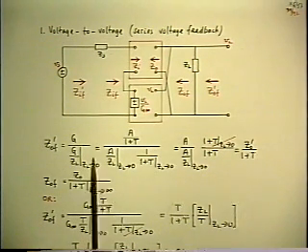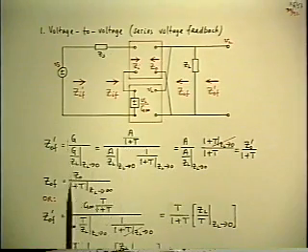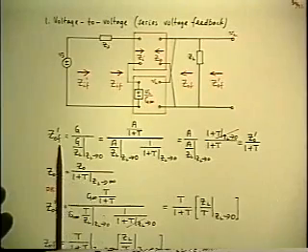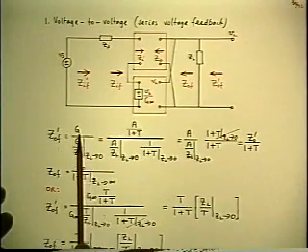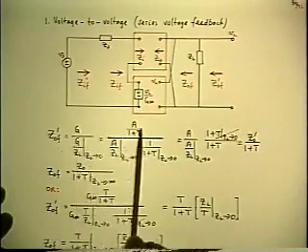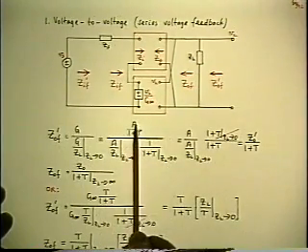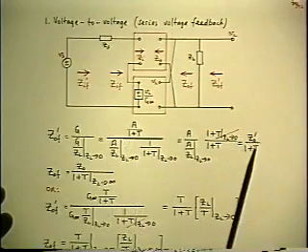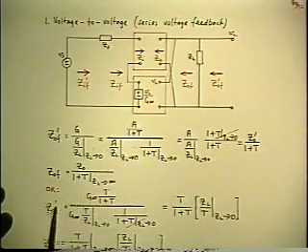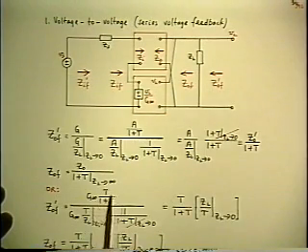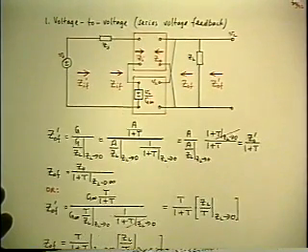And so the trick to do that is, in the very first line, when you want to apply the output impedance theorem, instead of substituting for the closed loop gain G in terms of the open loop gain A, that's where the open loop values got back into it. Now we don't want to do that. So substitute for the G in terms of the new version, G infinity and T, which are the quantities we're interested in.